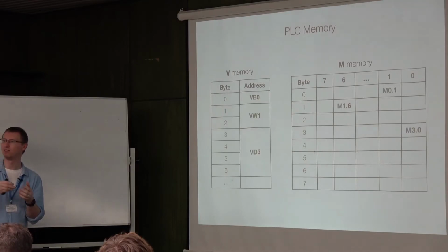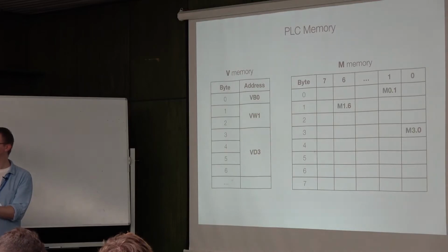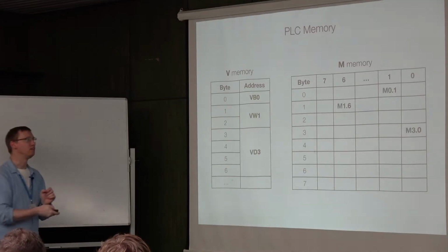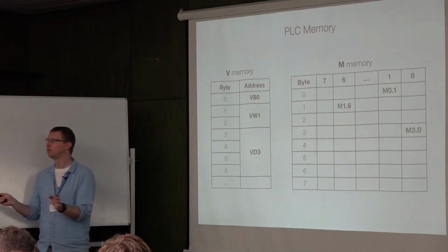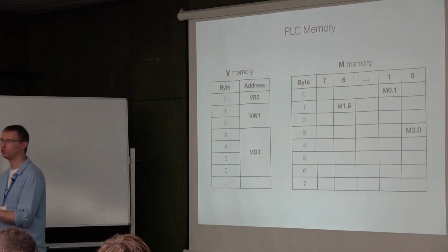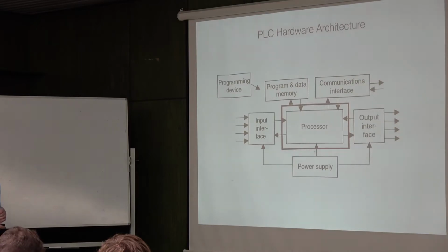Otherwise, you will end up with a memory table which is full of holes. So there is plenty of space, but nothing really fits in those tiny areas. So we have to reschedule everything. And we have to do something similar for bits. So just the takeaway note. There are PLCs, many of them, which require manual allocation of the memory. Keep this in mind if you ever are forced for any reason to work with PLCs.